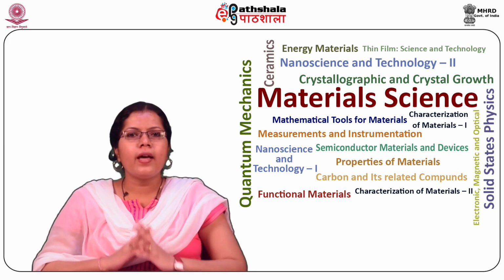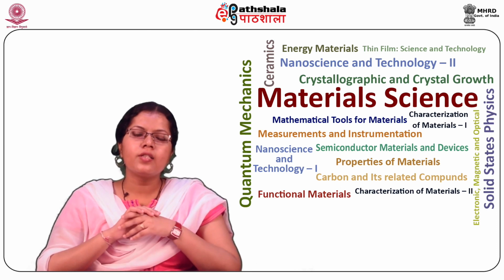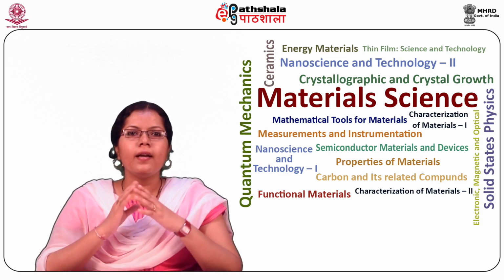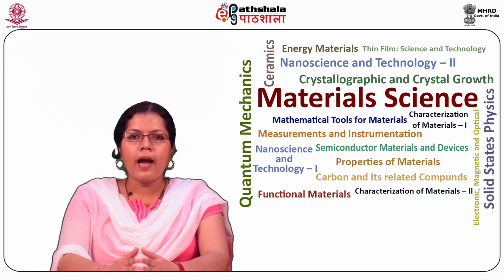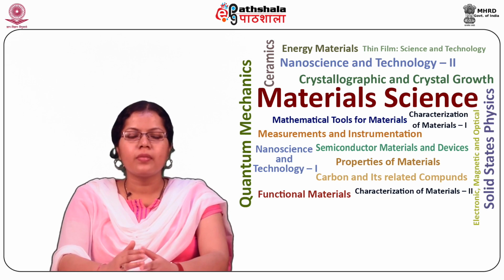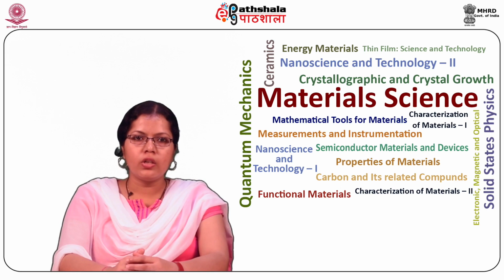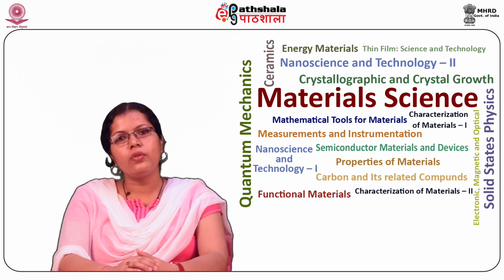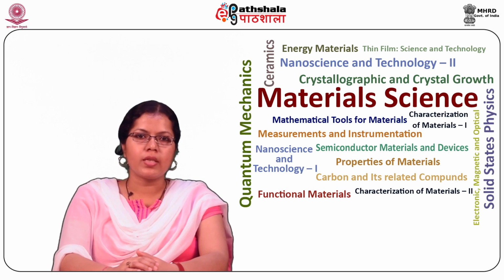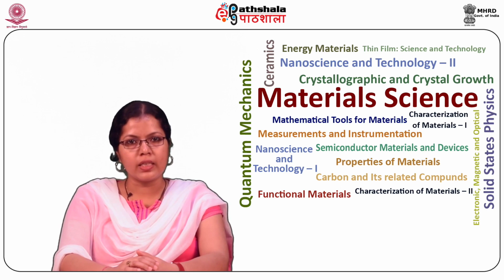The quality factor is a very important factor in electrical and electronic circuits and components, and it is generally denoted by Q factor. It is an extremely significant factor for the individual components. For an ideal inductor having zero resistance, the quality factor is said to be infinite and is defined as Q is equal to omega L by R. For a capacitor with no leakage, meaning no resistance, its Q factor is given by Q capacitor is equal to 1 by omega C R, which is again infinity.